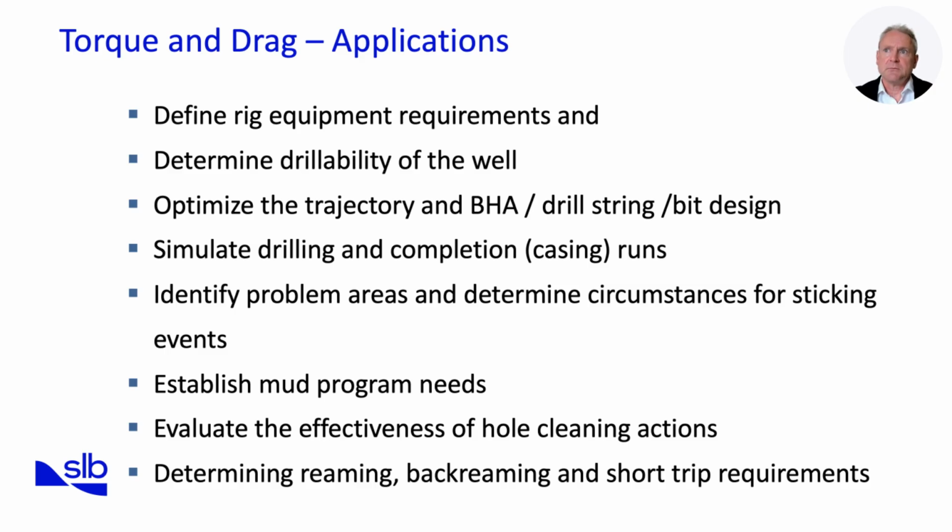Second, torque and drag models help us determine the drillability of the well. If predicted forces are too high, the design may not be drillable with the available rig and string configuration. Third, it allows us to optimize the trajectory and BHA, drill string, and bit design. By running scenarios, we can minimize friction, reduce side forces, and improve drilling efficiency.